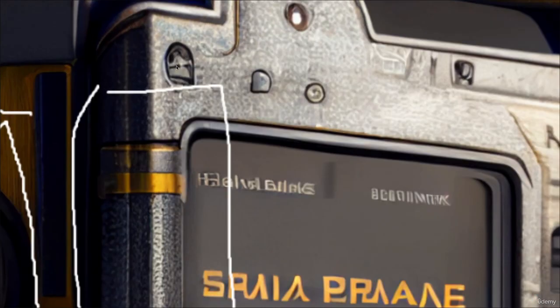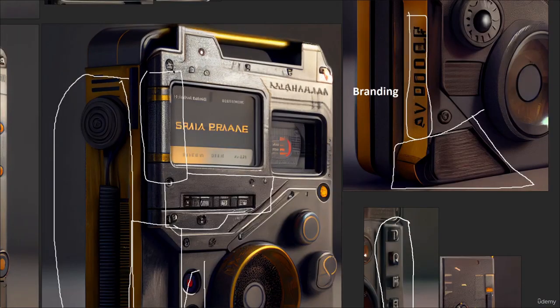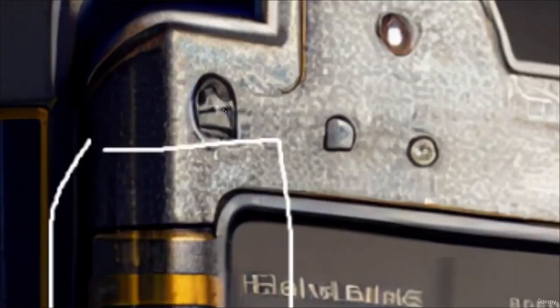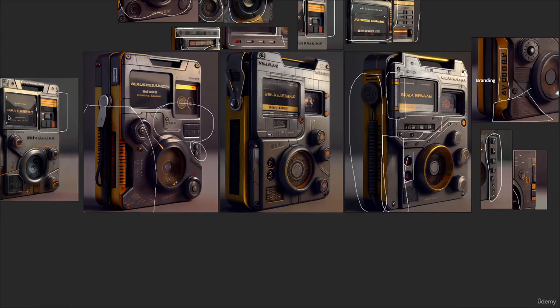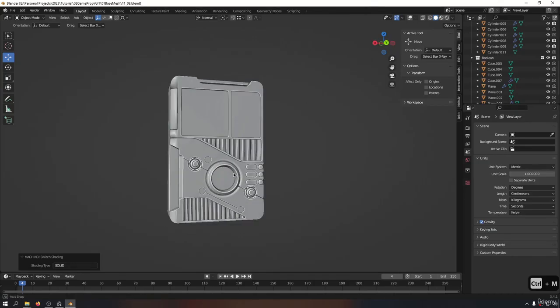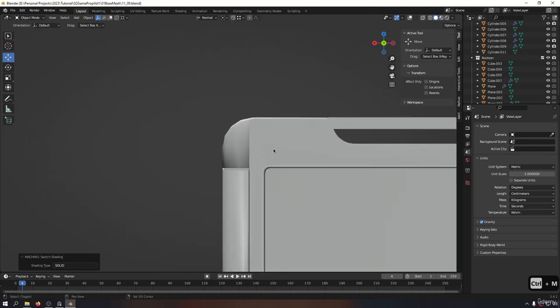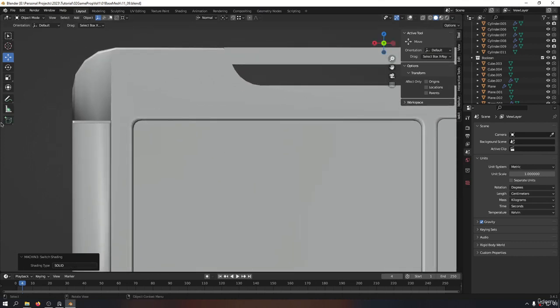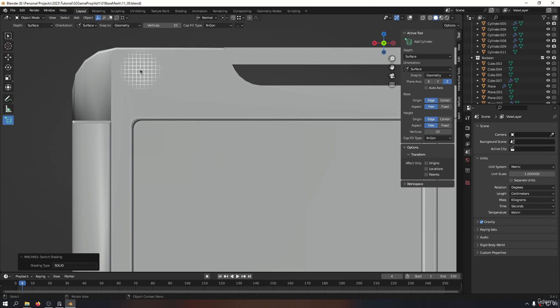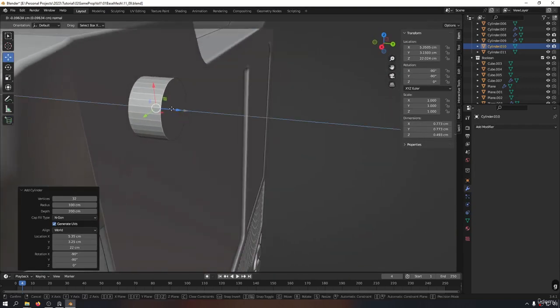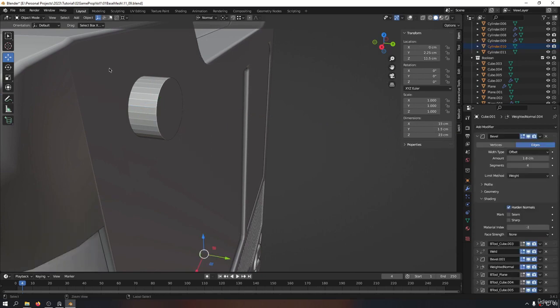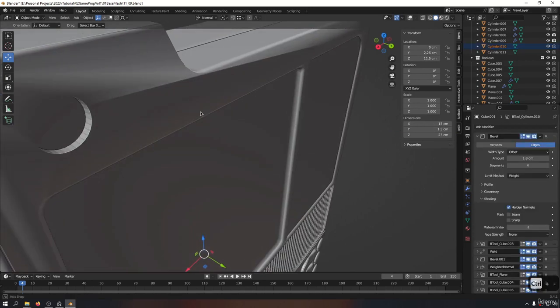And now it's time to create these bolts. It's going to be easy. We've done that before. We're going to place some bolts around this to create the illusion that this has been manufactured, and as a bit of storytelling. Okay, now let's create a cylinder right about this size. Hold Shift so that it becomes a perfect cylinder. Okay, now I'm happy with this. Let's drag it in and then take this one as the host piece, Control minus, to do the Boolean.